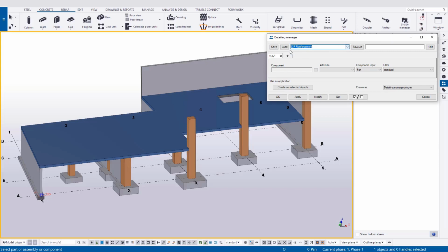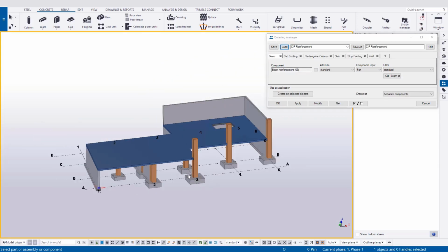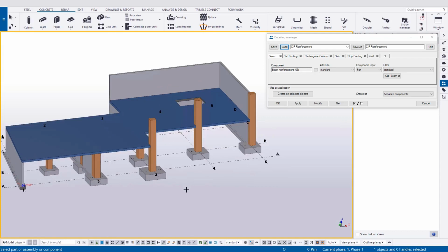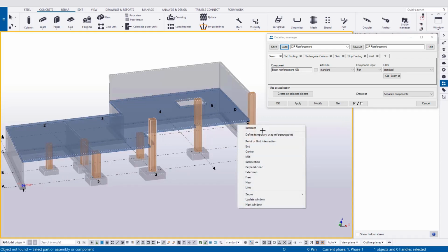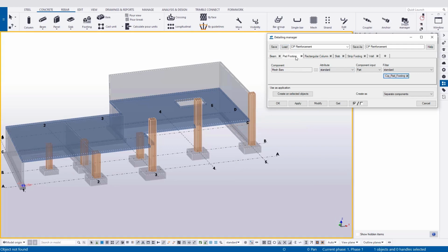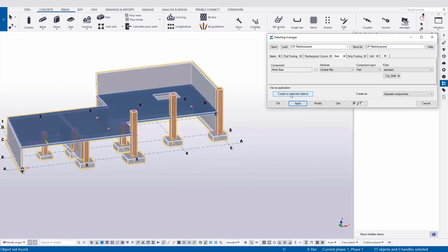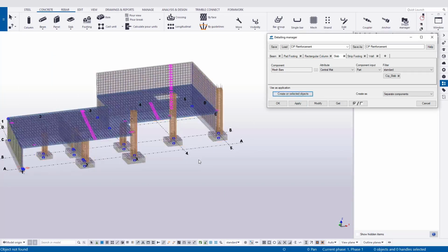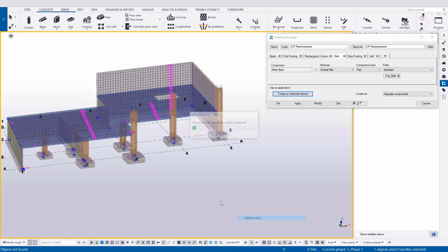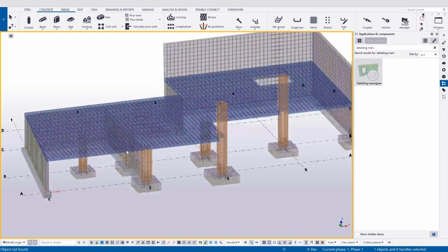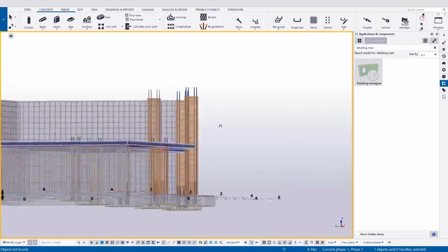Within the application, detailers establish a tab per condition they would like to reinforce, then select the component and associated save setting to apply to the concrete. The application uses filters to sort out what applicable pieces of concrete will receive this component and which ones will not. The Detail Manager already has a pre-built configuration that can be loaded via its drop-down, and users can utilize this right from the beginning or use it to establish additional or more detailed configurations. The key takeaway here is that once settings are established, detailers can apply components quickly and accurately with minimal setup time and are able to apply them all at once or through a methodical fashion.